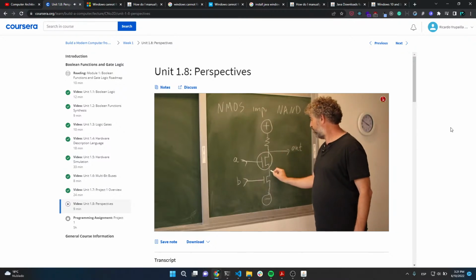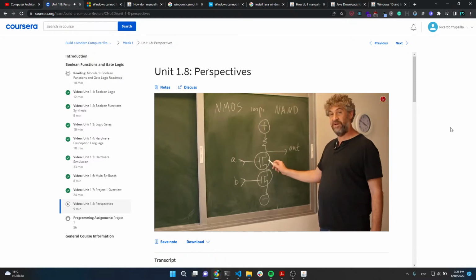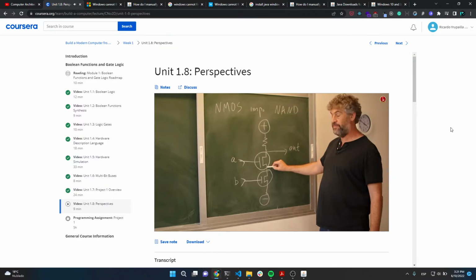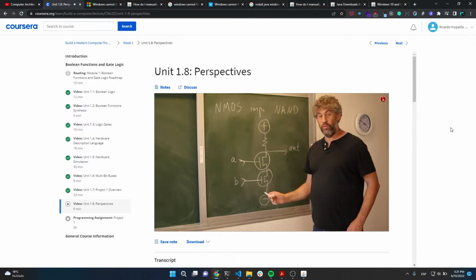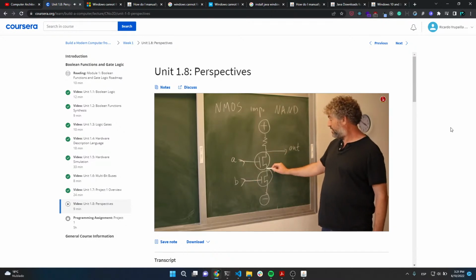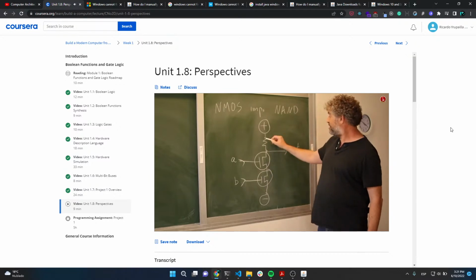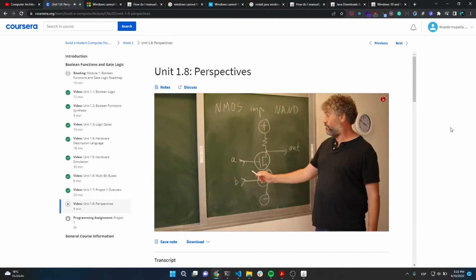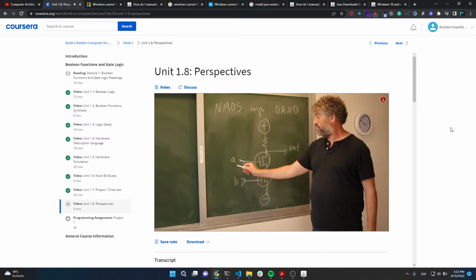So these are the two transistors that we have. How does this implementation work? The basic functionality of one of these NMOS transistors is that whenever the input gate gets high voltage, it connects the two other terminals. If it gets a negative voltage, it disconnects the two terminals. So let's see what happens. If both A and B are 1, then we get a high voltage here and a high voltage here. These two terminals are connected by this transistor, and these two terminals are connected by this transistor. So we get a connection all the way from the output to negative. Since this is a weak connection and this is a strong connection, our output is going to be negative, or 0, as we want in a NAND gate, because when a NAND gets 1 and 1 as inputs, it gets 0 as output.